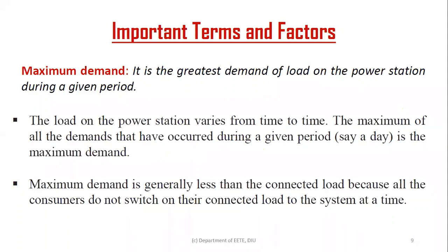So the maximum demand of individuals may not happen at the same time. That is the difference between individual maximum demand and the power station maximum demand. Here we are discussing the power station maximum demand, the greatest demand of load on the power station during a given period.